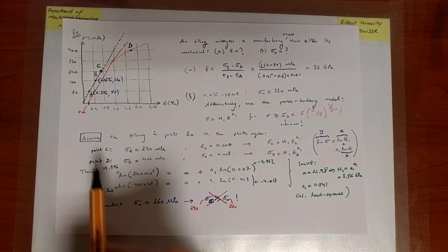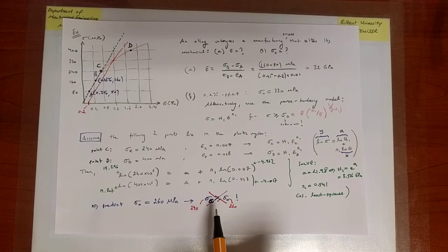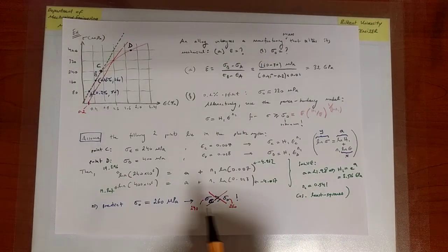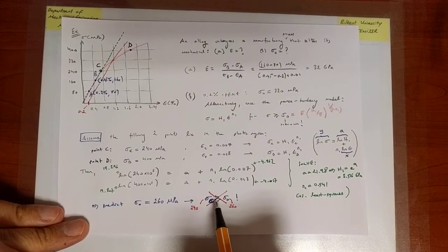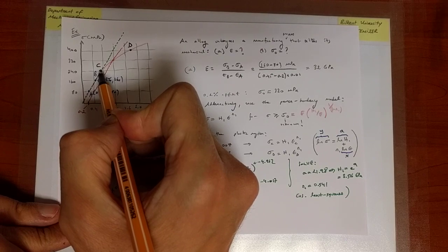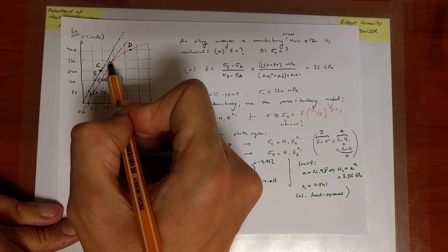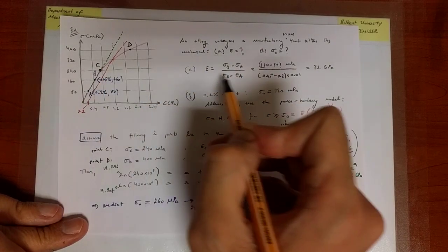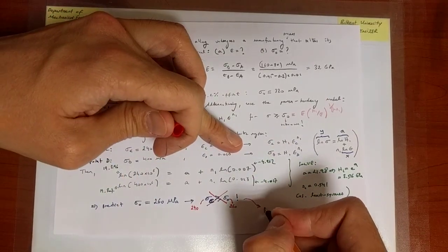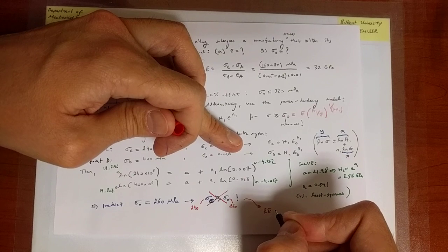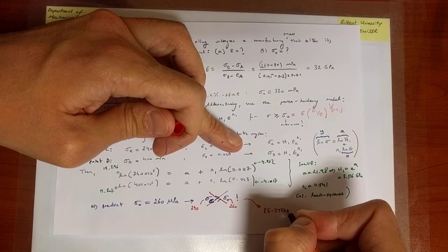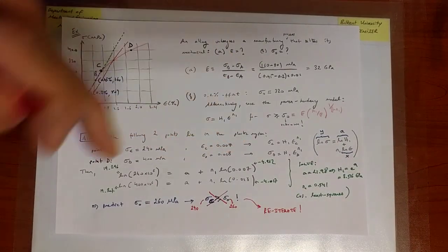And therefore my assumption was wrong, and I really need to now at this point go back and get rid of this discrepancy. I need to go back, pick a point, not C, not here, perhaps further into the plastic region, and then reiterate this process until I get rid of the discrepancy or I get a result that is consistent with my assumption.